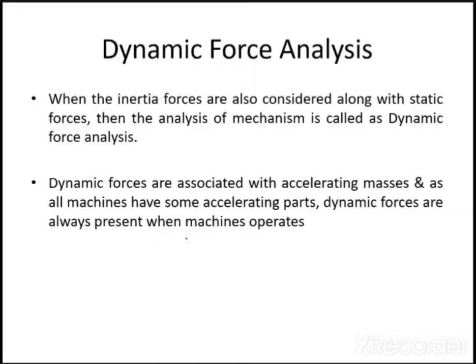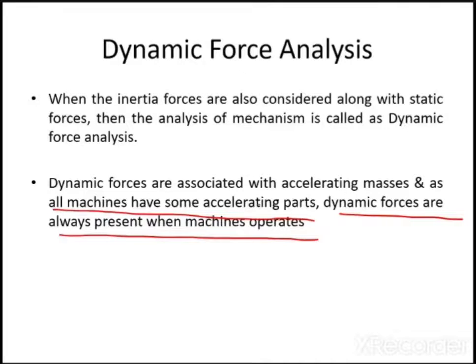Dynamic forces are always present when the machine operates. This is a very important statement. All machines have some accelerating parts, so dynamic forces are always present in that machine. Whenever the machine is operating under dynamic conditions, dynamic forces are always present. But if the magnitude is very small, we neglect it and call it static force analysis.